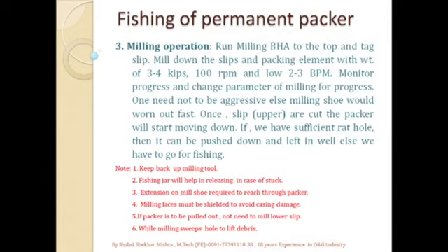Here we have to take care that we should not be aggressive in milling, otherwise the shoe would wear out quickly. And once the upper slip is milled down, the packer may start moving down, and if we have sufficient rat hole, then we can push down the packer to the bottom and leave it in the well.